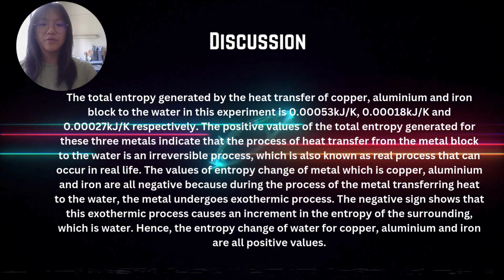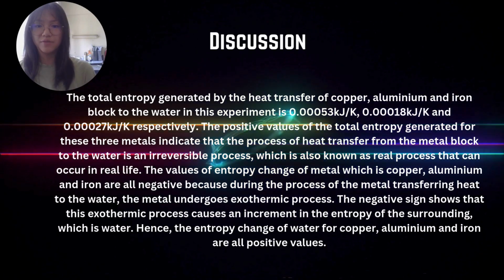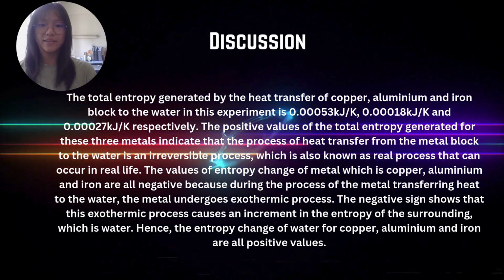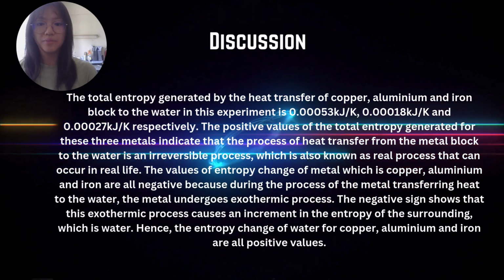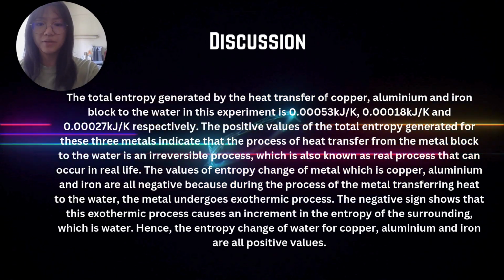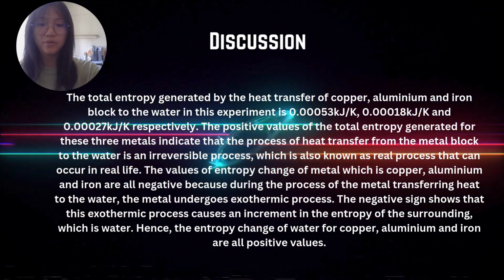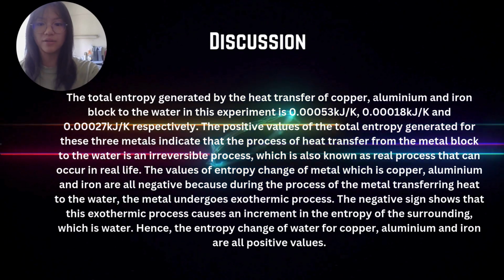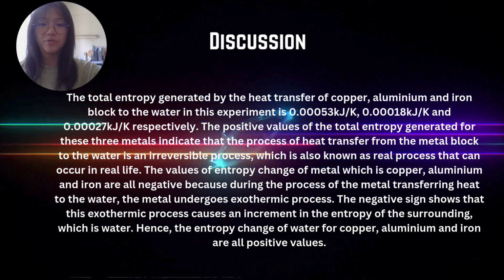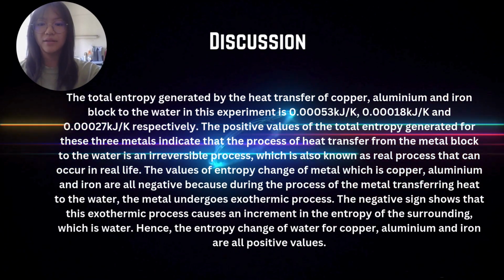The positive value of the total entropy generated for these three metals indicates that the process of heat transfer from the metal block to the water is an irreversible process, which is also known as a real process that can occur in real life. The values of entropy change of the metals, which are copper, aluminium, and iron, are all negative